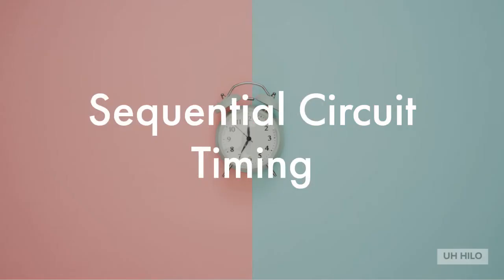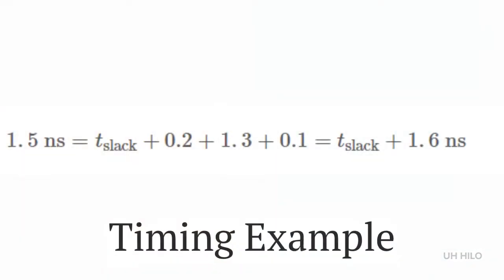In particular, each of these paths has three components: a flip-flop propagation delay known as TPD-FF, a combinational logic delay through the chain of gates along the path known as TPD-COM, and a flip-flop setup time known as TS. As the signal change propagates down the path, it's delayed successively by an amount equal to each of these delays. Let's look at an example.